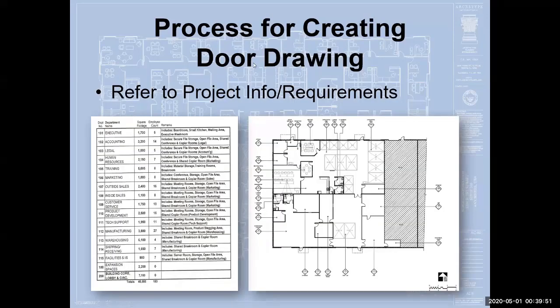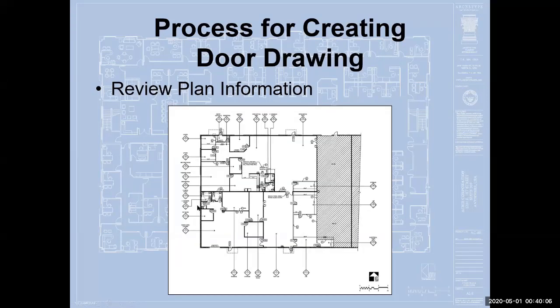So with that, we can start to look at how we actually produce this information. As we've talked about, it starts as we look at the program and the space plan that the senior designer's done, we go back to our construction plan, and we start looking at doors and figure out a strategy for numbering them in a sequential way, so that door 101, door 102, door 103 is not some haphazard number like 1, 6, 3.